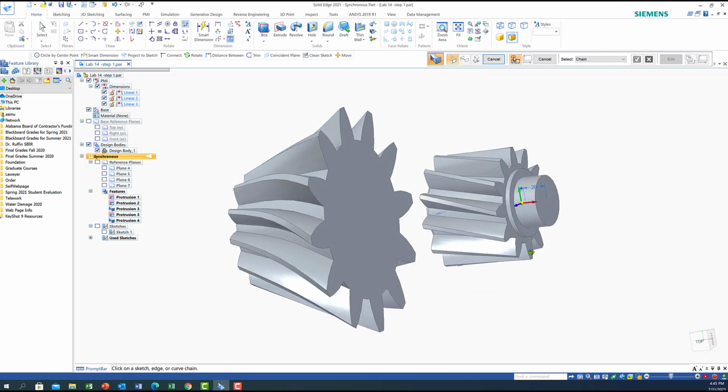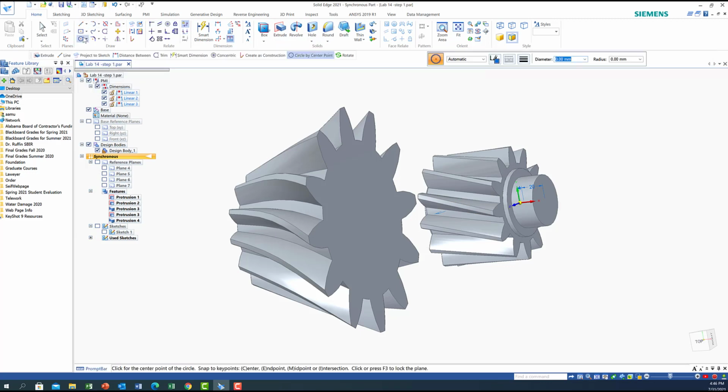Now we need to build whatever we have here. So now what I'm going to do is come to this location and draw the two circles so we can connect them. So now I'm going to highlight sketch, circle by center. One of them is going to be 60. Enter. And then I move it to the plane. Click on F3, means that it's going to be in this plane. When I go to the center, the concentric, I'm going to click. So that means I got the 60.